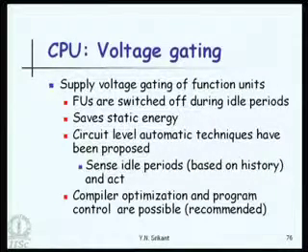So, let us say 2 cycles of inactivity trigger switching off of the supply voltage to the function unit, and it remains in that state until the function unit is required again. Once it is required, the supply voltage is reactivated and the function unit becomes functional. But both the switching off and switching on require some finite amount of time. That has to be factored in when we want to actually use this technique in the architecture or through the compiler mechanism.